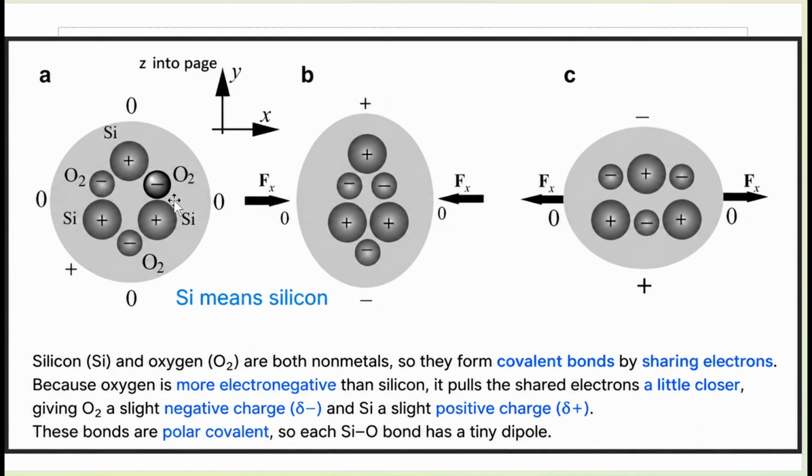In a quartz crystal, we have silicon and oxygen. The oxygen harbors the electron a bit more, holds it a bit more, so it's more negatively charged than the silicon. Now, in a normal case where we don't put pressure on the crystal, all the forces cancel out. But if we do put a force, say here, we put a force out. Now here we can see the structure changes a bit, and now the top will be minus because we have more minus, and the bottom will be plus, okay? This is probably a very simplified example, but this is what we had in our textbook to explain how the piezoelectric effect works.